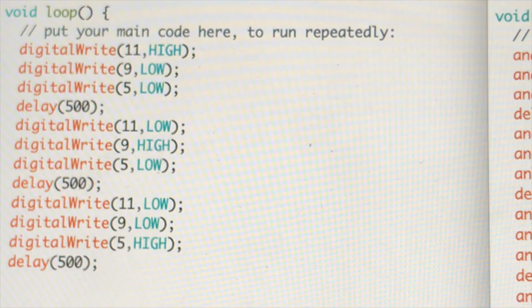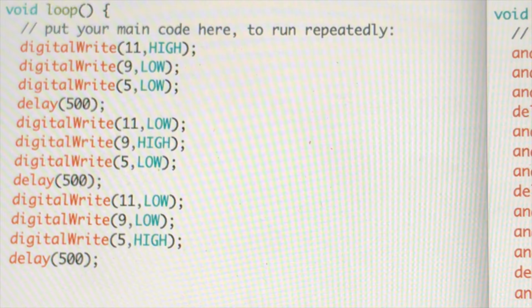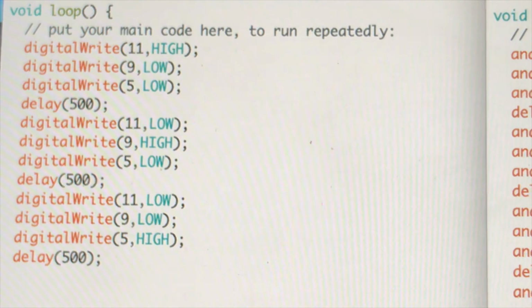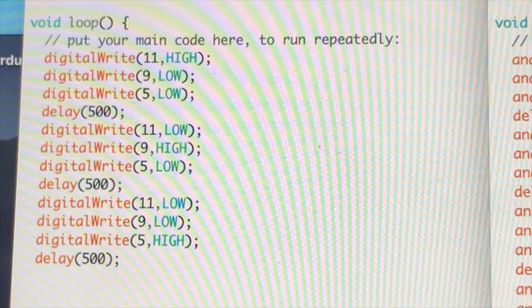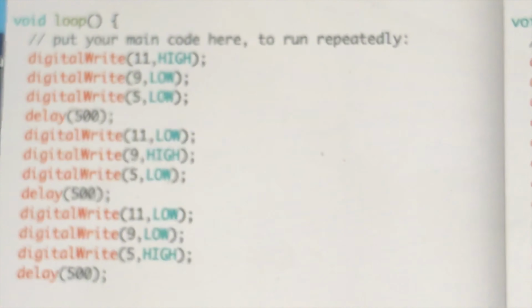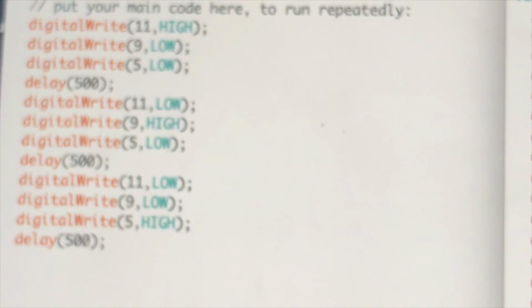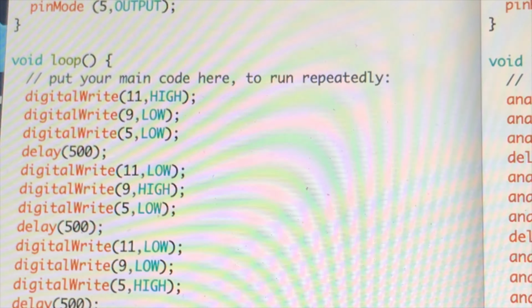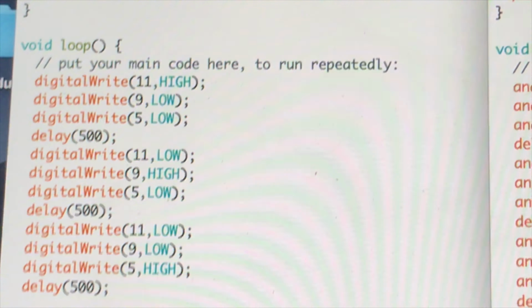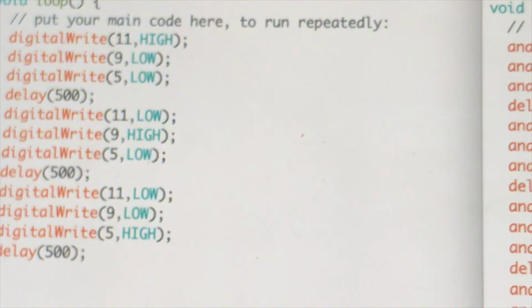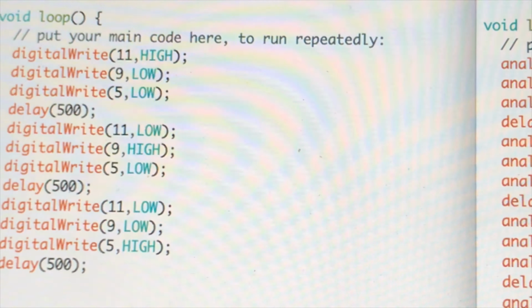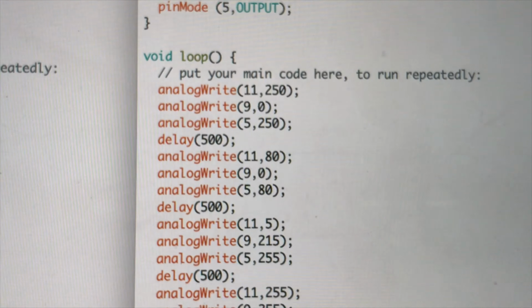So for question 2, you keep the wiring, but all you have to do is minorly adjust the code. In question 1, we've been using digital, high and low, because we're just turning on the simple colors, RGB. We just want them to turn on and turn off. But to get these unique colors, you want it to blend a bit. Remember the 0 to 255? We have to adjust with those brightness values. So instead of digital, we want to use analog.